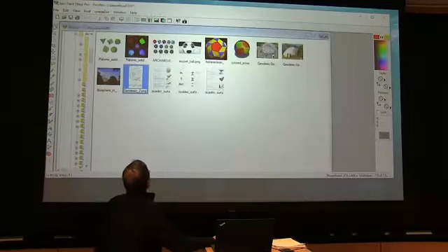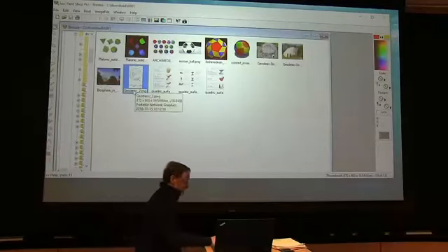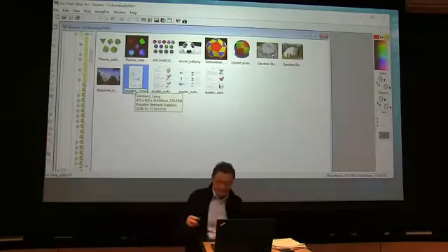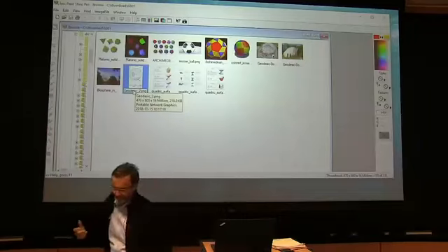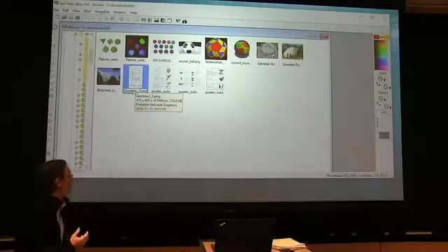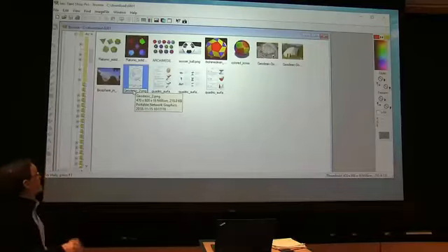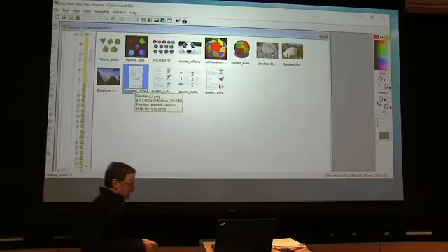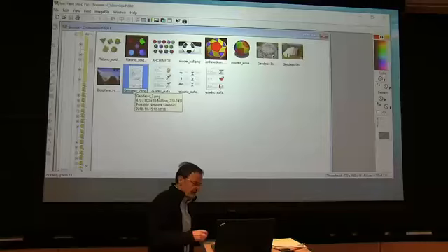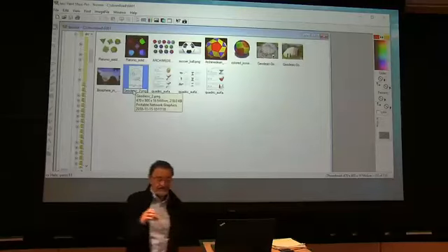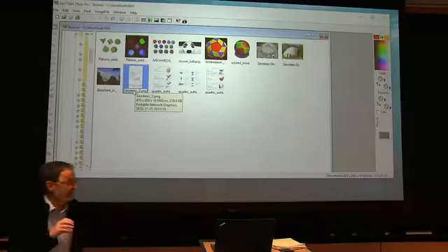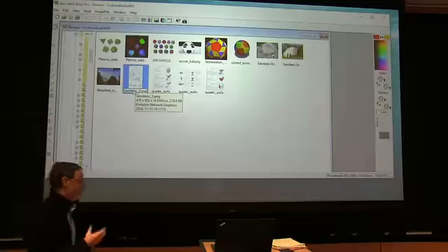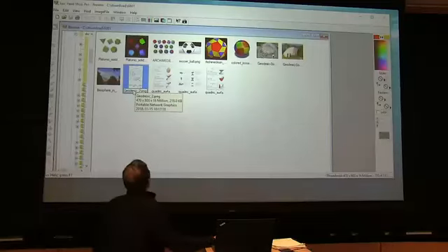Okay, and again, the geodesic dome for us has a number of features. One of them is that the facets aren't all exactly the same size, which is undesirable, and then they're triangular, which is undesirable. So we're likely to instead use the dual, which would have a larger number of hexagonal or approximately hexagonal facets and some number of, well, 12 pentagonal facets.